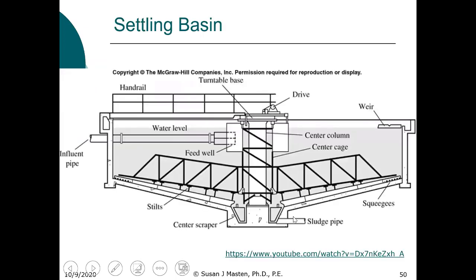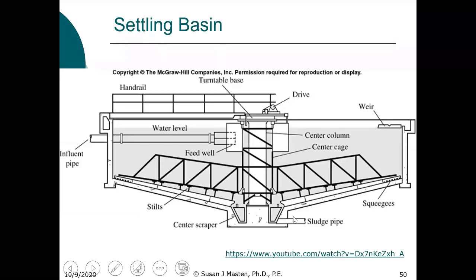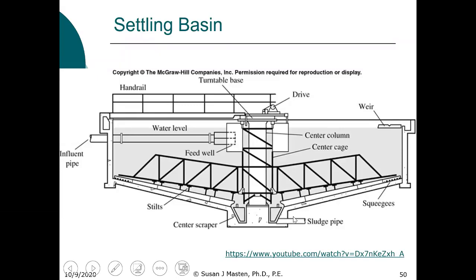Okay, so let's continue with sedimentation. We'll finish this today. So what I want to look at today is more of the design aspects. We've looked at type 1, 2, 3, and 4 settling. We've looked at how we predict removal efficiencies for type 1 and type 2, and discussed the fact that type 3 and 4 are much more difficult to estimate or predict removal efficiencies because of the interactions between floc